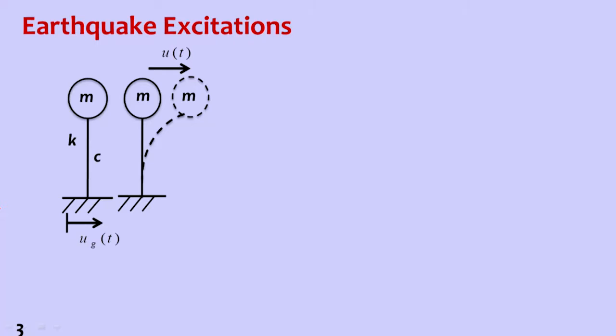If you look at this closely, what is actually happening is, in this one you can see u_g is the ground displacement. So this part is moving up to this part. This ground is displacing from here to here; this is u_g, the ground displacement. And then when the base of the structure is stopping here, the mass is not stopping there, it is going further. So that is u_t, that is the displacement of the mass.